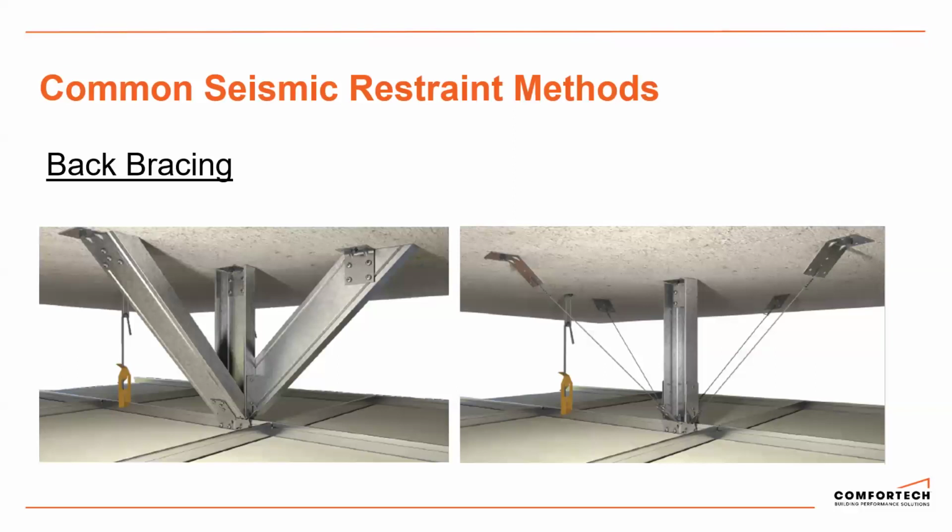Wire is obviously not as strong as steel stud. So often, we may have to have a couple of extra braces. And so that just needs to be factored into that design, but it's a really handy and useful tool that we can look to use where plenum spaces are either really big or really crammed.